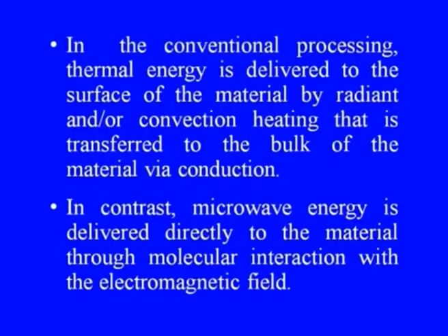In conventional processing, thermal energy is delivered to the surface of the material by radiant and/or convection heating, which is transferred to the bulk of the material via conduction. In contrast, microwave energy is delivered directly to the material through molecular interaction with the electromagnetic field.